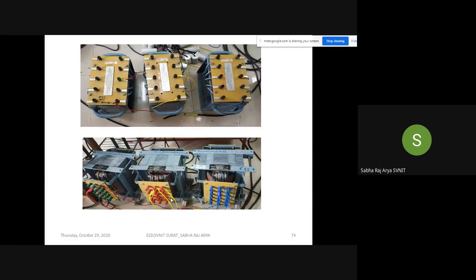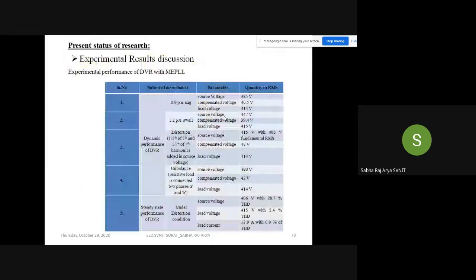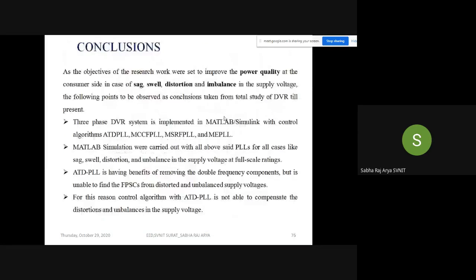Now in this next point also you can see, as we always say, we have an injection transformer. These are the injection transformers to inject the required compulsory voltage at the load end. Also, if we don't have a sufficient value of inductor, then we can add some extra value of inductor also, so that we have proper compensation. Okay. Clear?